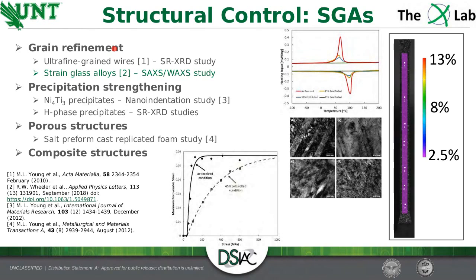Thermally, if I continue to load this, it's kind of hard to see here, but the red curve is the as-received material. As I put in about 15% cold work, it decreases that peak. I go to 30%, it decreases even more. At 45%, we see the phase transformation completely disappear. So when we cycle the temperature, there is no phase transformation. That's thermally. But mechanically, we still see that it loads and behaves like a shape memory alloy, so fully recoverable.